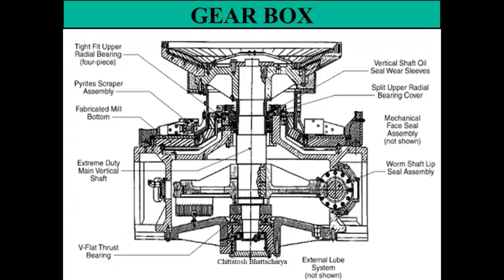From the top bearing there is a passage through which this lubricating oil passes through a lube oil flow sight glass, through which the oil flow can be continuously checked and monitored. There is also a cooling arrangement for the lubricating oil supplied to the milling gearbox, with continuous water flow across it.